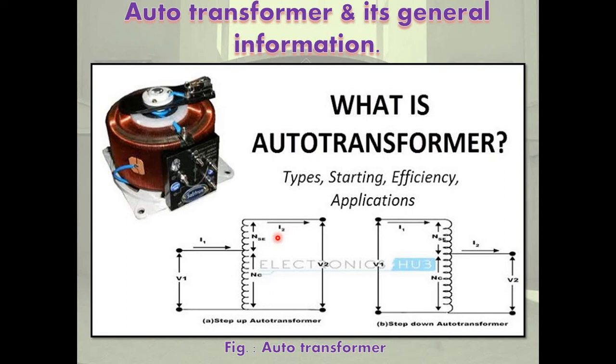Now, what is the phase sequence and how is it changed? The phase sequence refers to the cyclic order in which the voltage waves of three phases rise to peak values, like R, Y, and B. A small indicating instrument or phase sequence tester is used for testing phase sequence. If any two of the terminals are interchanged, the phase sequence becomes RBY instead of RYB.